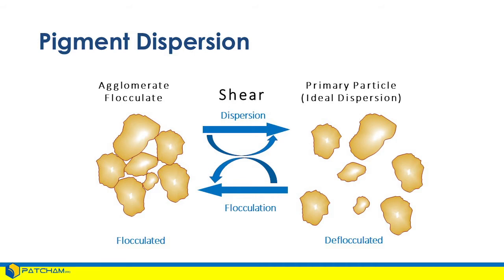So here in a diagram format, we take our pigment particles, which exist as agglomerates. These particles make contact with each other. Inner spaces are all filled with air, and there's surface air trapped on them. We wet them, then we subject them to shear. This is the dispersion stage. The reason we put that energy in is that we want to separate these pigment particles. So we have to overcome the force of attraction of these particles, and your dispersion force must be greater than the attraction forces holding these pigment particles together.